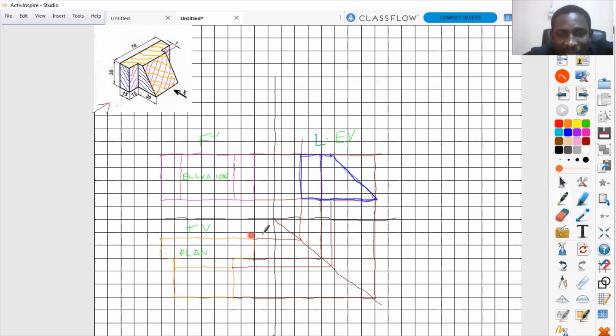Now the idea of these projection lines is to help you get the end view quickly. You can also decide not to use that, but just transfer measurements from here to draw this. This whole drawing is actually supposed to be a sketch that will make whoever is producing these orthographic projections sure that you are getting what you want. So that if there's a mistake, you can quickly correct it on this before you move to your drawing sheets to make your drawing.